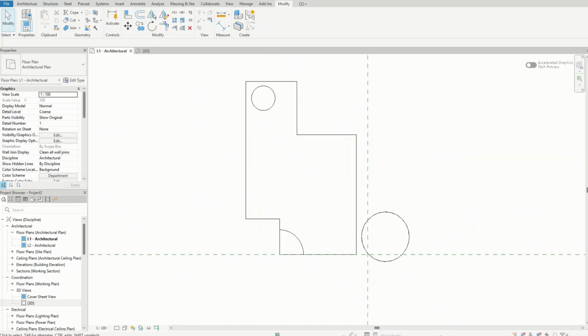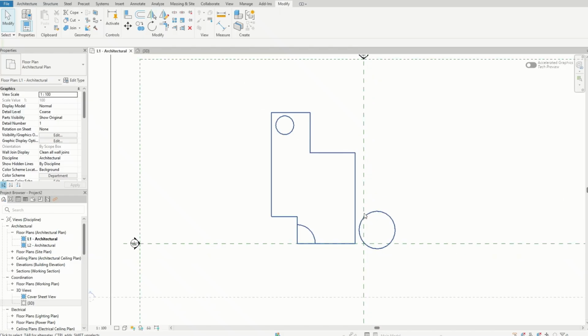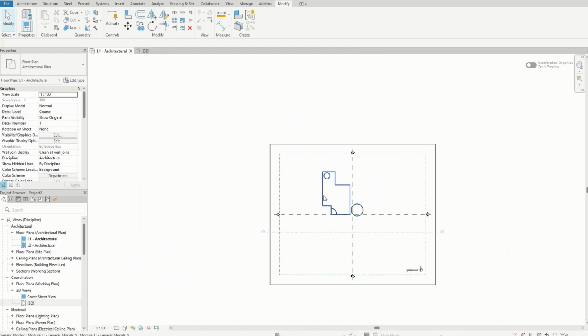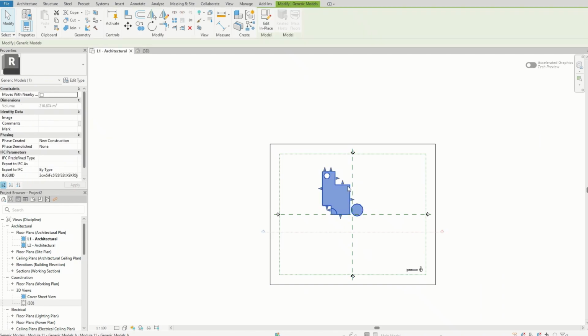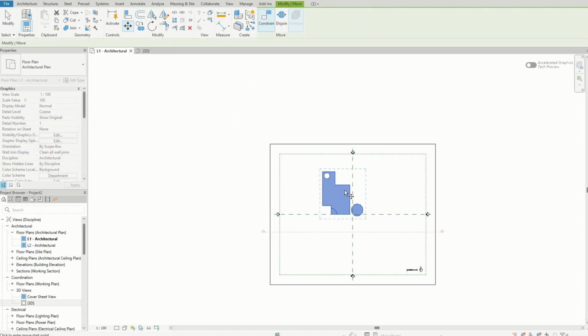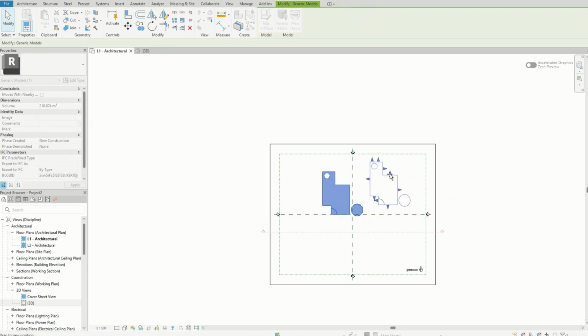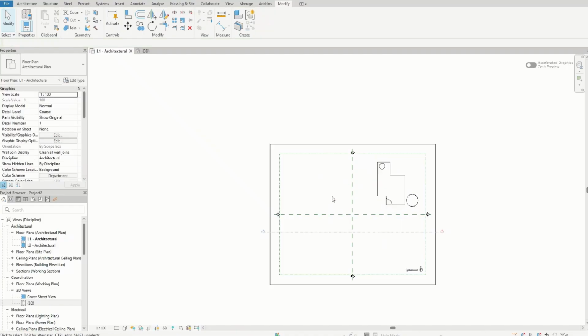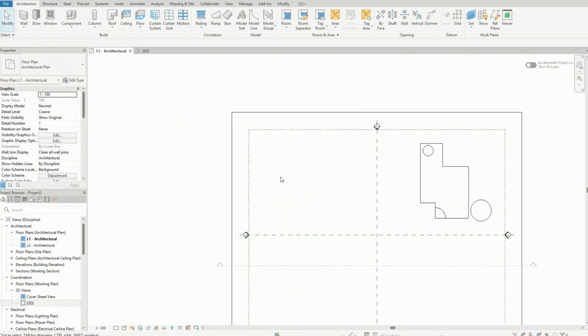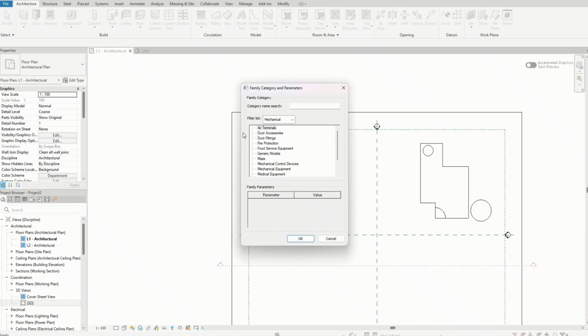Step 23 to 25. Reset and re-enter. In place, on level 0, either delete your previous form or move it aside. Go to Component, Model In-Place, pick Generic Models, accept the suggested name, and continue.